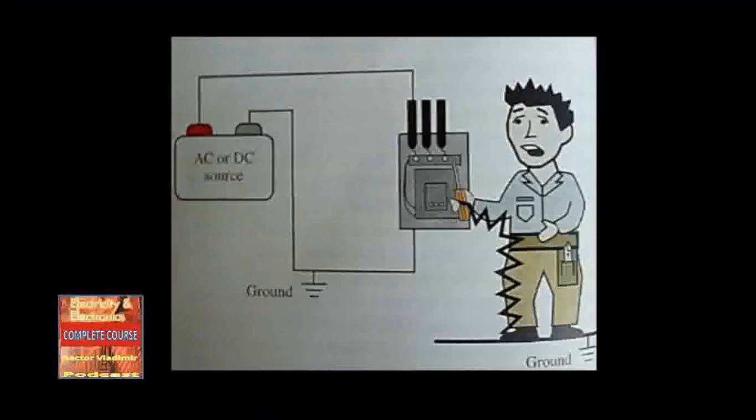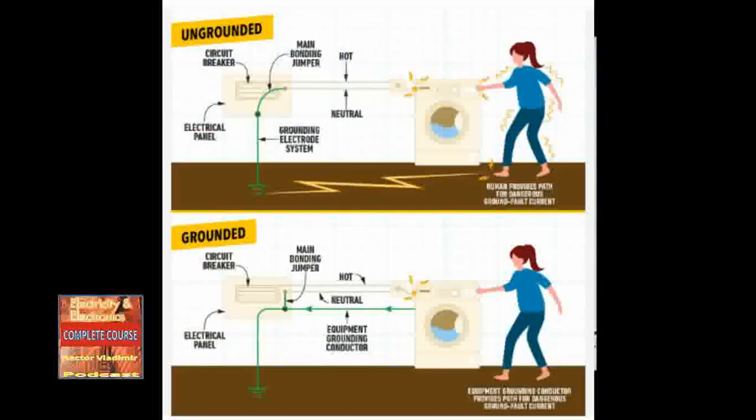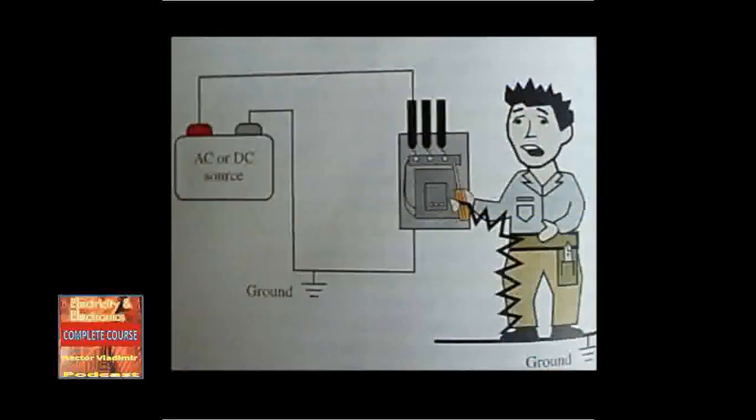Electric shock. Almost all electrical systems contain a ground. A ground provides a safe path for an electrical fault and has a 0-volt potential. It is typically constructed by connecting a conductor between one of the electrical system conductors and the earth. On AC systems, the neutral conductor is grounded. On DC systems, the negative conductor is grounded. Some electrical systems do not connect directly to the earth. Instead, the metal enclosures or metal conduits serve as a ground or as a return path for current.